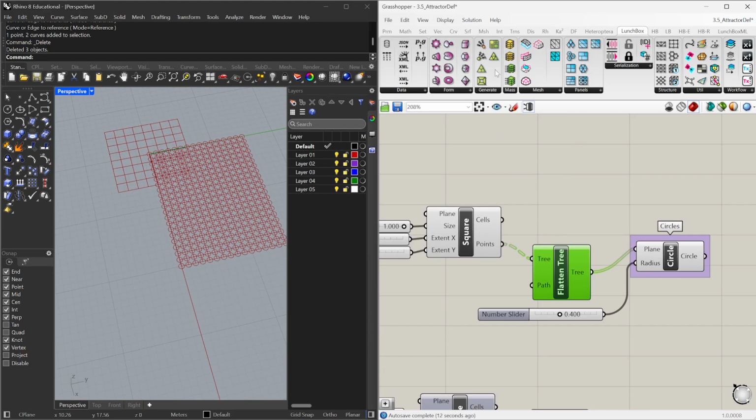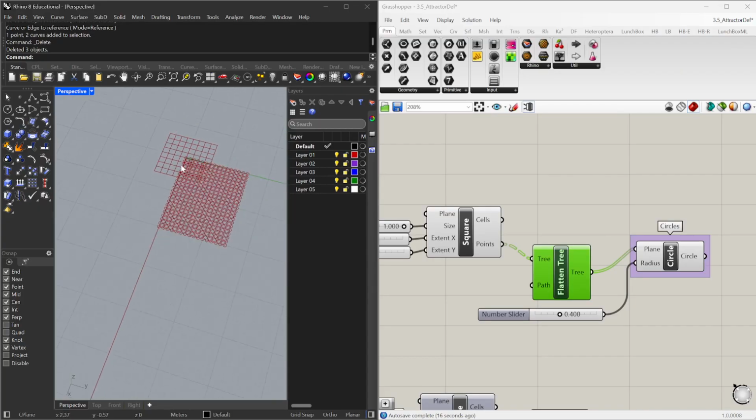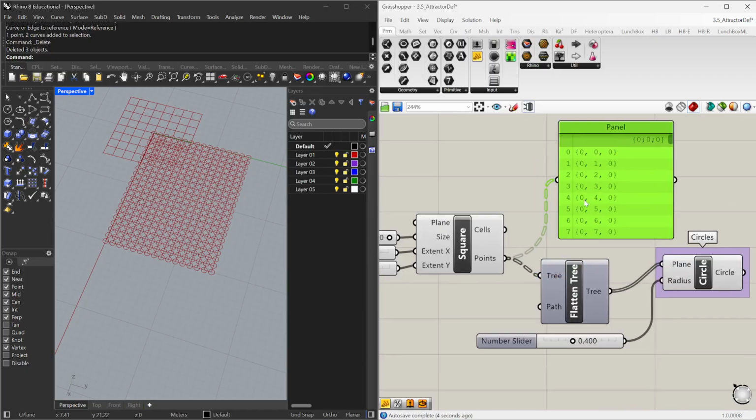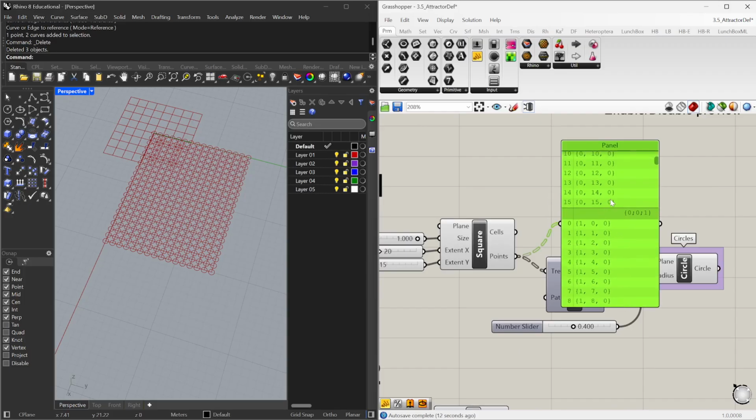The way that data works in Grasshopper, what's happening right now with our grid, if I just plug it into here, you can see that 3 numbers are being output all the time. So we have 0, then 1, 2, 3, 4, 5, 6, 7, 8, and then all the way to 15. Then our next row starts, and it's like 1, 1, 1, 1, 1, and it's going to give us every single column.